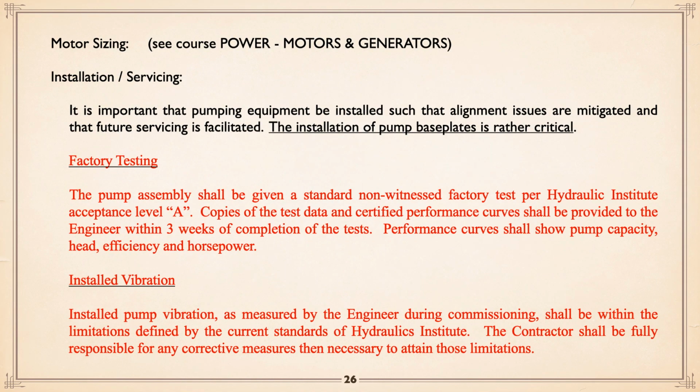Motor sizing. We do have, later on, we'll get into motors and generators. And we'll get into the fact of how the base for a pump is installed, which is very important. And here we have a typical specification which calls for factory testing. In this case, as we recommended, acceptance level A, and hydraulic vibration, which is tied down by Hydraulic Institute. And again, the requirement that the contractor and his supplier have to meet Hydraulic Institute standards for vibration.